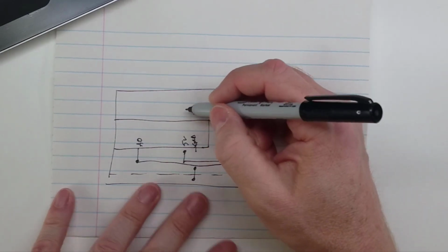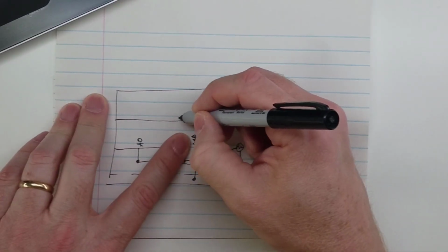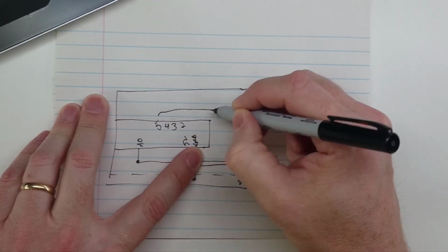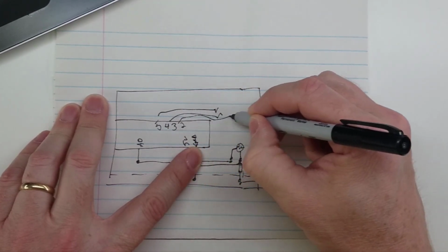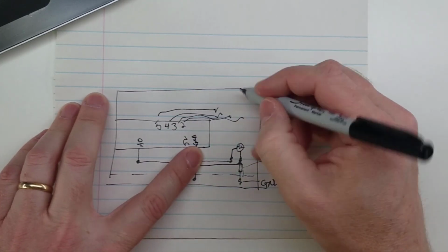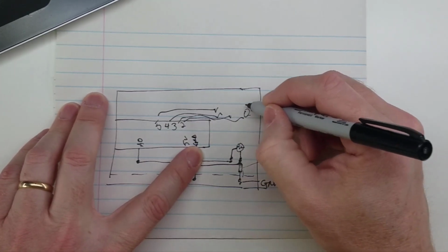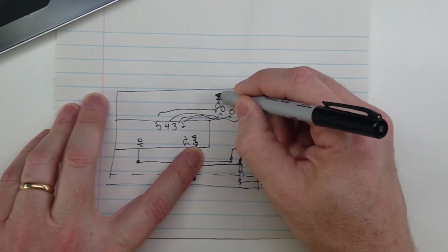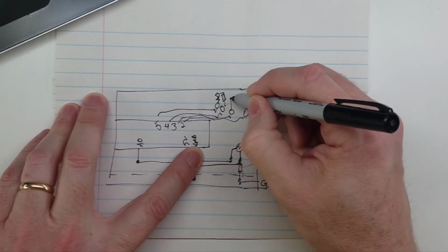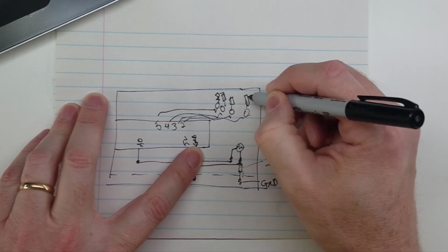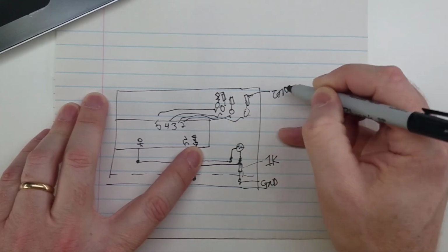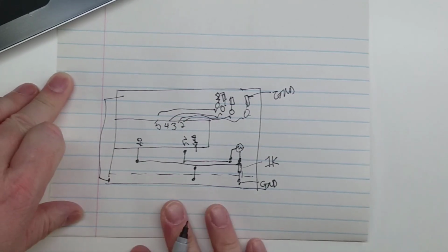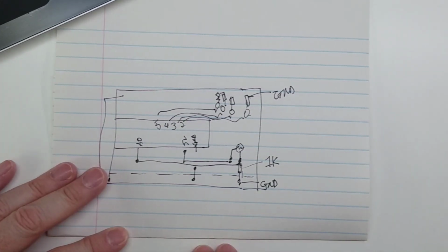And then if you want to put the LEDs on, over here I used 2, 3, 4, and 5. You can just simply run a wire over to the other side of the breadboard and then put in each of your LEDs and then run them with a resistor, one of the blue resistors, to ground. And then make sure you run a wire from this ground to this ground and you'll be all set. So that's all there is to it. Pretty straightforward.